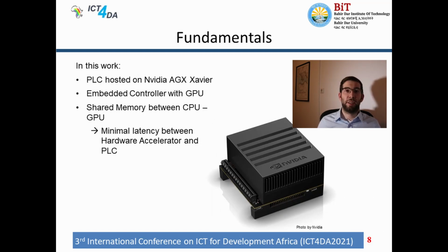In our work, the PLC is hosted on an NVIDIA Jetson AGX Xavier board. This is an embedded controller with a shared memory between CPU and GPU, allowing to share data between the both with minimal latency, and thus allowing hardware acceleration of the PLC with almost no latency in data copy.